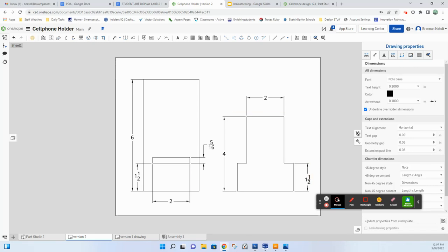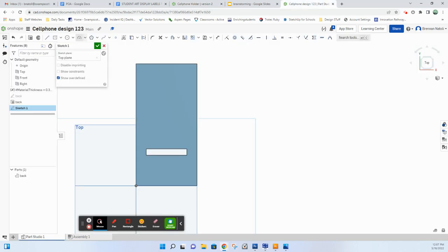So what I need to do is first go back. I'm going to create a line, and I want to create a construction. This is a reference line. So if you go up here in the toolbar, there's an icon for construction or Q on your keyboard. I'm going to click, drag this up, make sure it's vertical, and I'll make this 4 inches. Keyboard's getting stuck right now. Sorry.